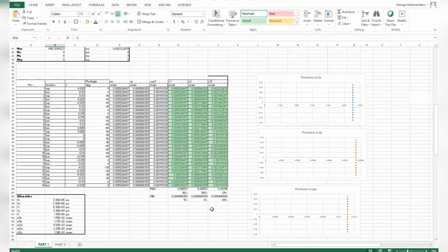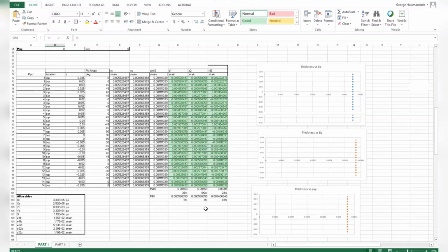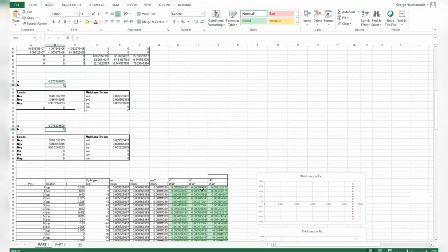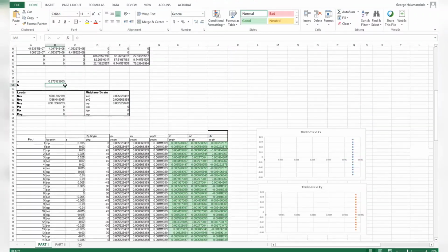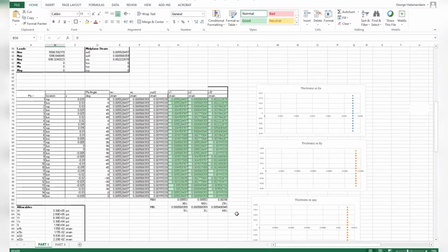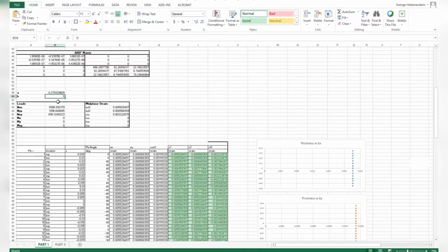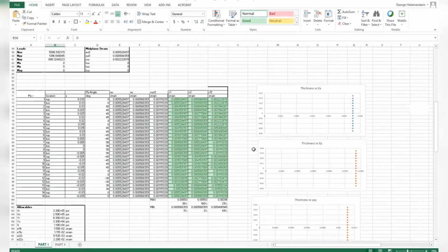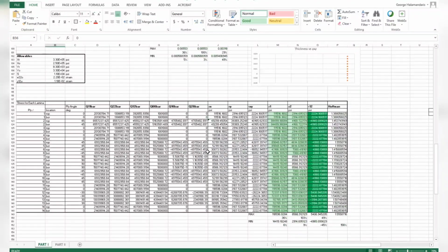And so again, that's just passing, and the 100% here indicates that you're riding right up against your allowable. So we'll do something similar for stress, and so that would inform, for your strain criteria, you could accommodate 27% of the load input before you induce failure.